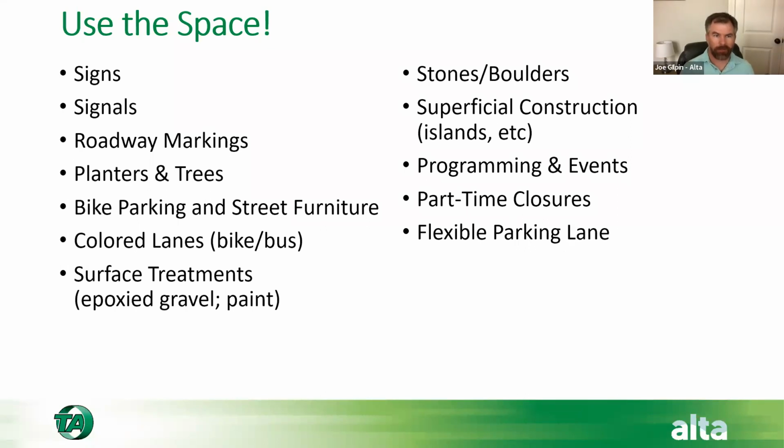And is it just bike lanes, or can we do more things with a retrofit type project? And yeah, we can put simple paint and traffic markings and signage down, but we can also apply color and surface treatments and put planters and barriers and all types of things out in the street in order to create some of the geometry that we're looking for that we might not be able to do as a permanent or long-term project. There's a lot of elements that we can use in terms of quick build, in terms of our resurfacing and retrofit type project works that allow us to do that.